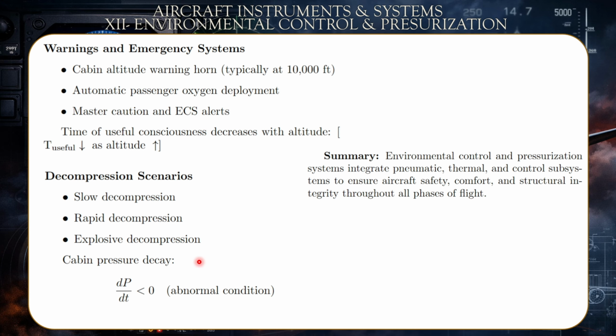And third, explosive decompression. This type of decompression would rip the airframe apart, okay? Like in one of the instances, it was a flight over the ocean. I don't remember the number of the flight, but what happened is that the decompression actually ripped off the entire upper part of the fuselage, okay? And by the way, in some instances, it brought airplanes down. So it can be very serious.